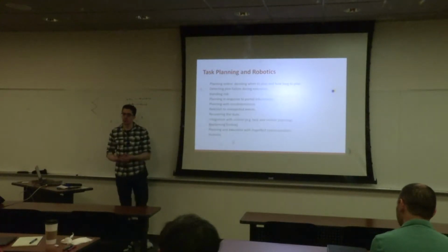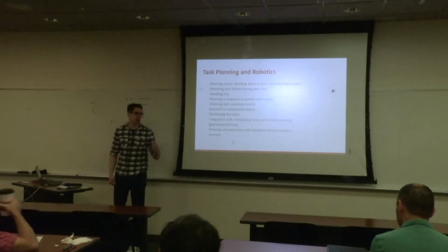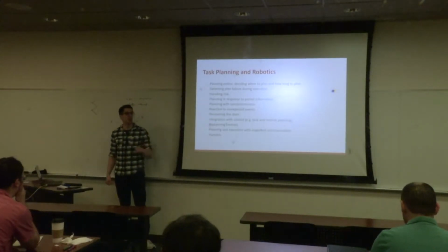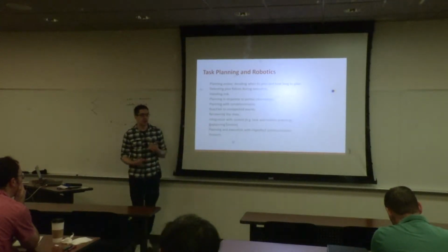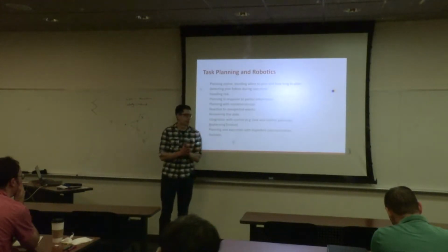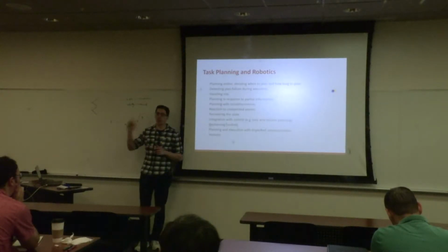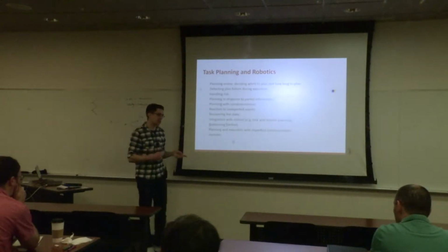How do you recover from that? Our PDDL state is an abstraction of the real world, which only models parts of it. And right now we're between PDDL states. And how you recover from that will depend on exactly what kind of state space you're looking at. For this waypoint example, you could just say, we're always going to assume that the robot is exactly at one of these waypoints, just whichever one it's closest to. But now your model's inaccurate in a different way.